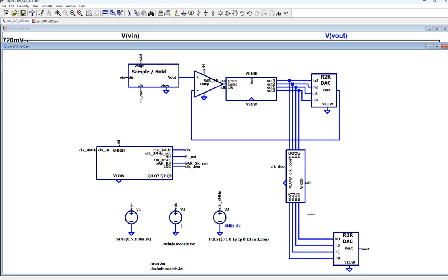That's why it's a rising edge triggered D flip-flop. We need it here because we only want to send all the D's to Q at the rising edge, but not anywhere else. We don't care what happens before and after the rising edge, only at the rising edge. If the data is ready and correct, we send it out.